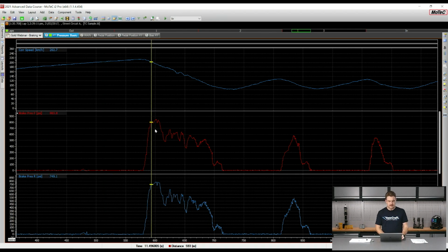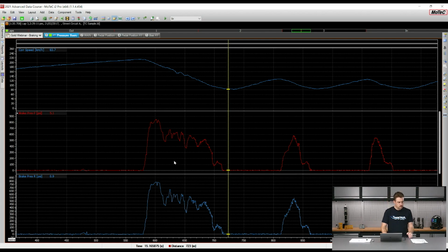So as the driver moves through the stop, he makes more or less his biggest brake pressure at the start of the stop, and then he's sort of gently bleeding off the brake pressure here. We'll talk about some of these features a little bit later on in a bit more detail, but he is bleeding off the pressure before bleeding completely off, and as he gets to mid-corner here when the speed is the minimum, he's got no pressure on either of those hydraulic cylinders.